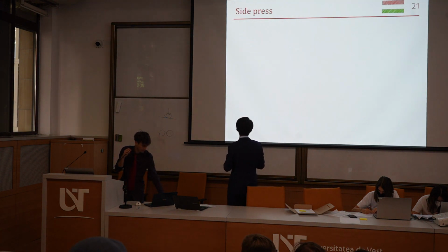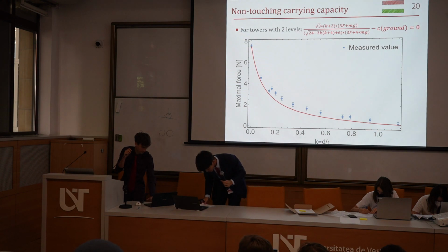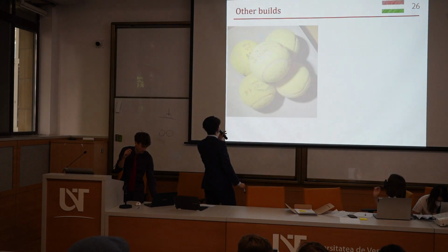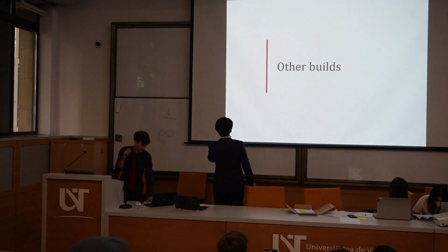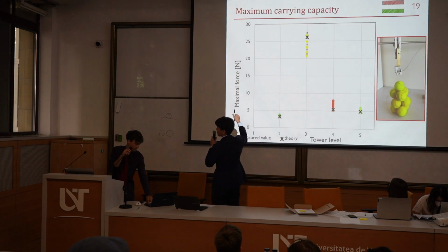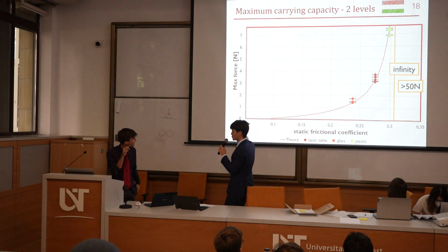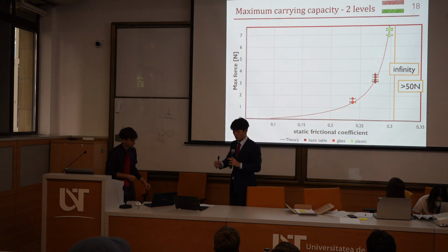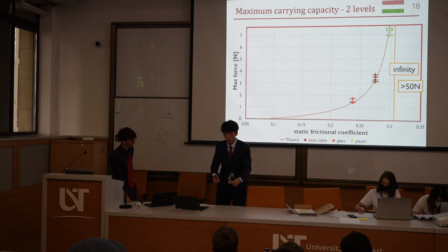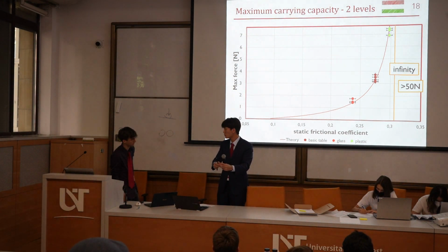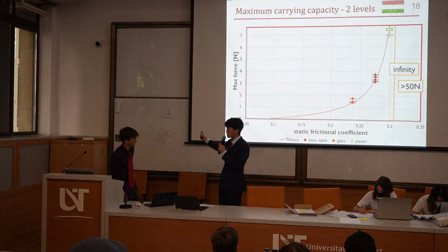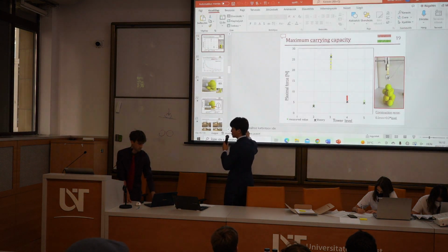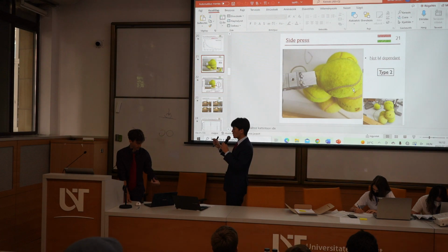Yes, so you can see the horizontal. No, sorry, the previous one. You can see that the value over here is relatively small. So this is the true thing that causes the tennis ball tower to collapse, the horizontal one. It's the true reason, because if you think the tower collapsed due to the big vertical push, the only vertical push on the tower is the top ball, which is 60 grams, right? So it is not logical. The thing that causes the instability of the tower must be the horizontal push. So here, are you talking about these measurements? Yeah.